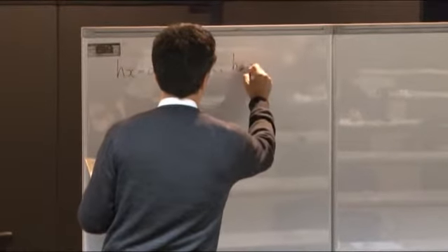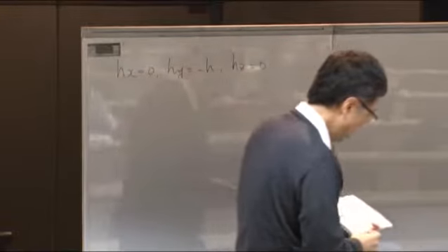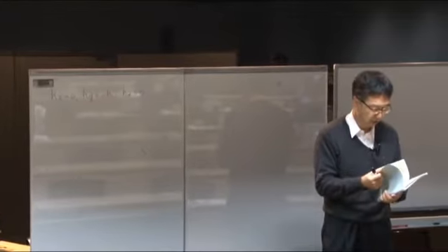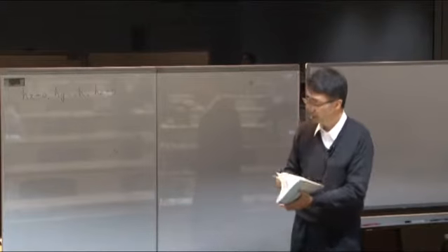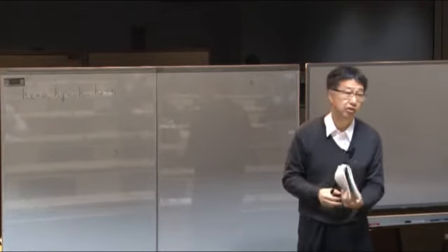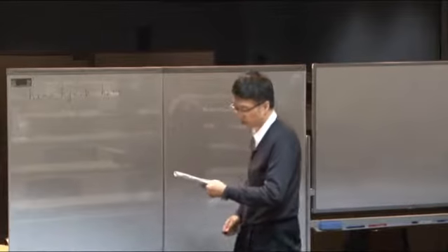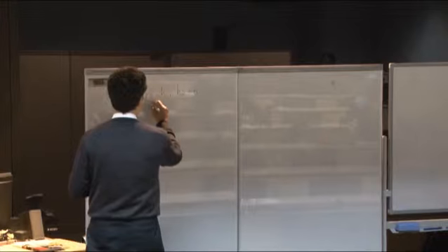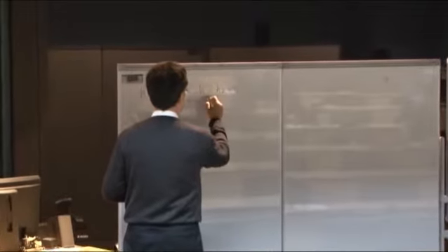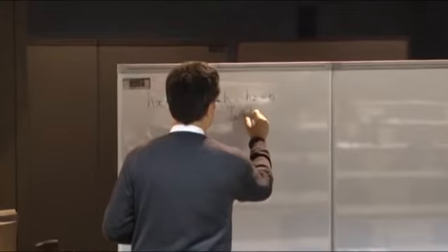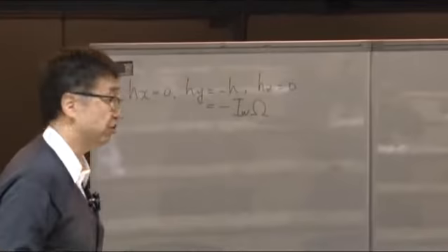And so this is the internal momentum around the XYZ axis. Internally, only one wheel is usually installed in the y-axis, and so only the y has the internally biased momentum. So this minus h can be written as I_W large omega.